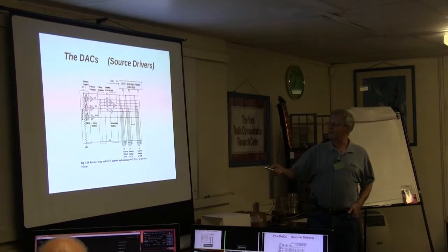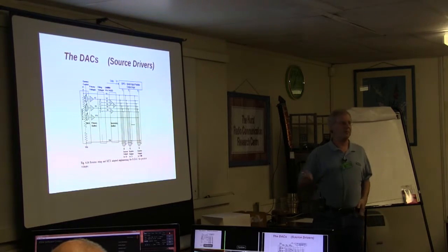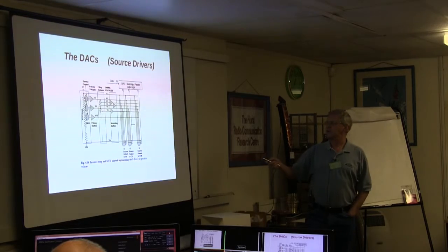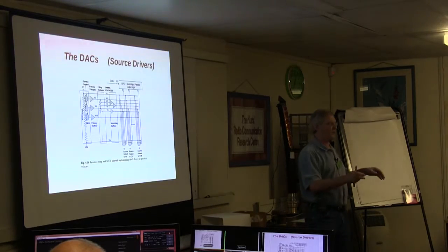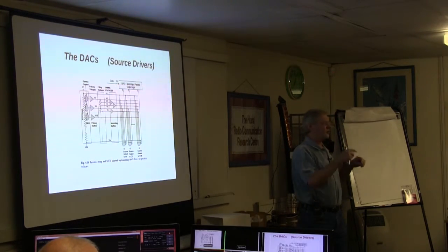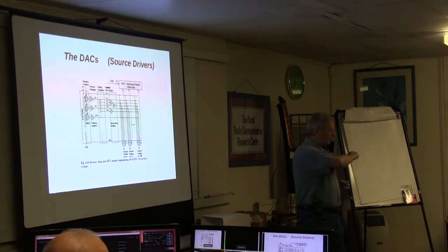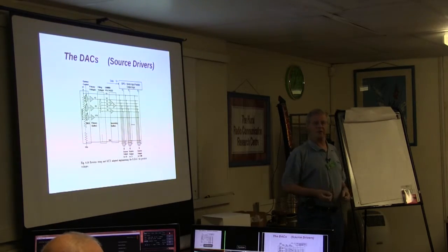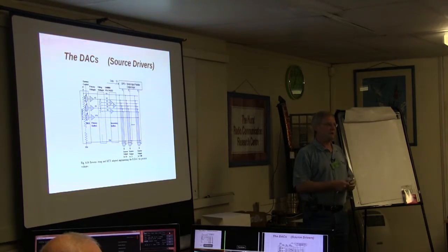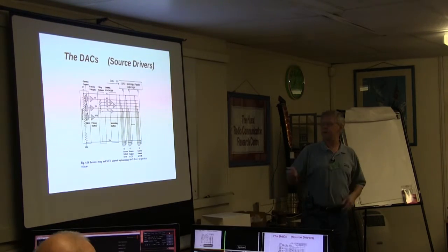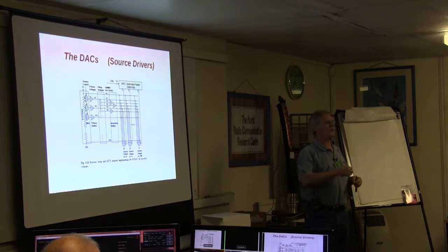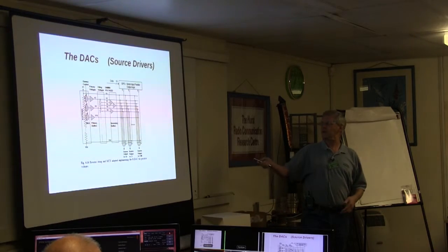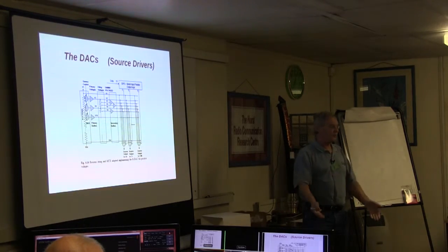So when I came in, this is where they were using these high-speed buffer amplifiers, because there's a lot of switches out here and they're all going to connect at once, and then on the next line the voltage may be different, so they'll connect to a different tap point. So there's this big load of capacitance going onto this reference voltage and it pulls it away from the reference voltage. So the op-amps had to be quite quick, with fairly high current capability. These were typically 5-10 milliamps peak, but they had to provide a little bit more than that because they needed to get all the stray capacitance out here charged up or discharged quickly.